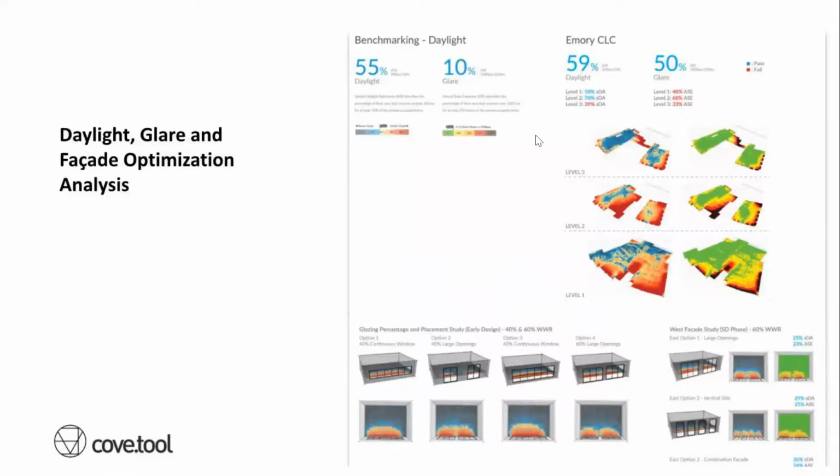And so a little bit about their daylighting. I believe at this point they're currently using 2 to 3 bounces to get their daylighting. You have some ability to adjust the test point size, so you can get faster models. This is probably the element that takes the longest to run. It takes usually a couple of minutes compared to everything else, which is 30 seconds to a minute. The optimization can also take a little while, depending on the number of variables that you're using. This will give you an idea of the amount of daylighting.